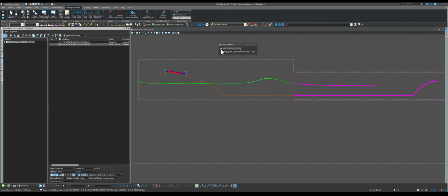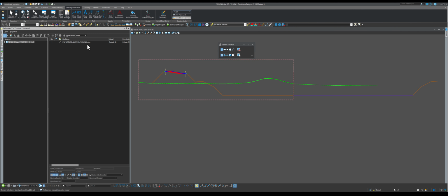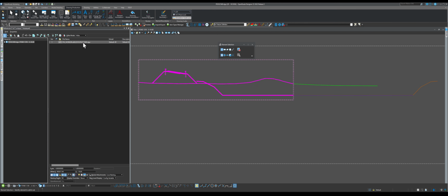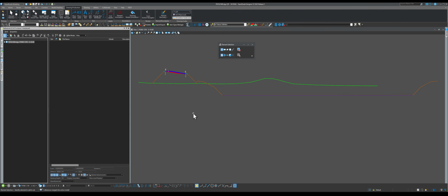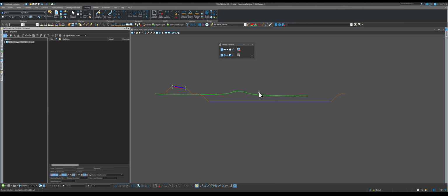And then let's select these both, and then just click one time, and as you can see here, it disappeared from here. And look what happened. It's already just a line here. And then let's go to the other one, right click on it, let's do merge into master. And it disappeared from here. That's it. So now there is no more connection to your 3D model.